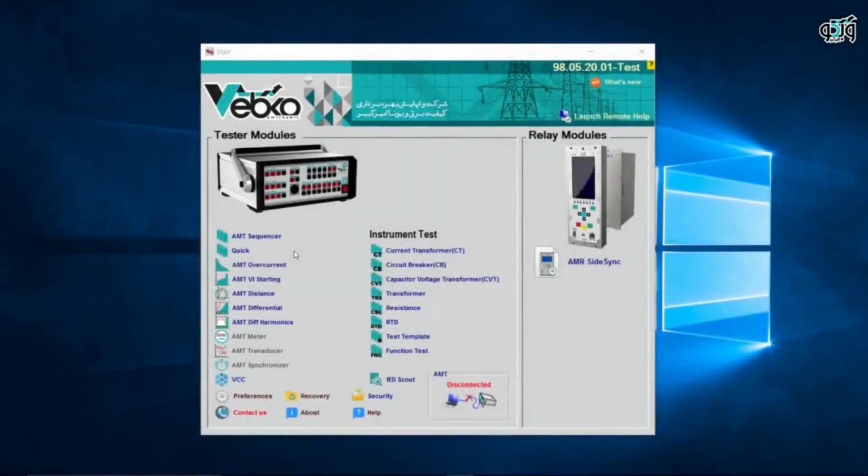One of the most essential tests to be performed on the lines that are protected by relays on both sides is an end-to-end test. To perform this test, both devices on the sides of the line must be synchronized and inject the required signals into the relays simultaneously. The first step is the stability test. There are two things to consider for the test. First, the transformation ratio of the CTs, and second, the polarity of CTs.